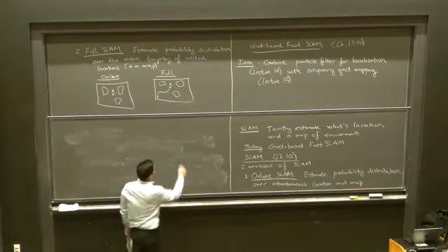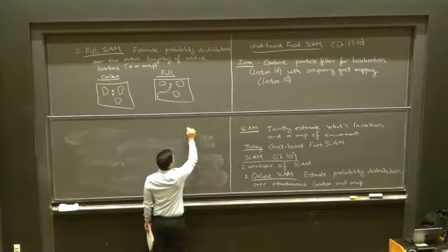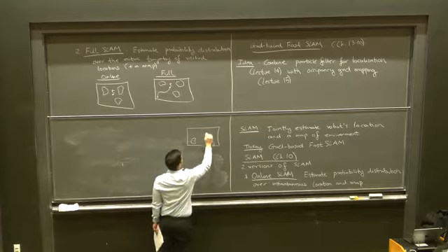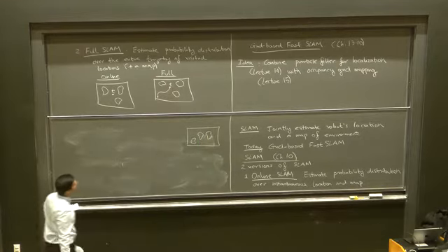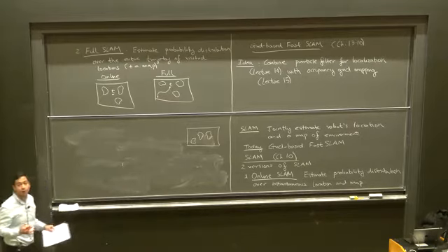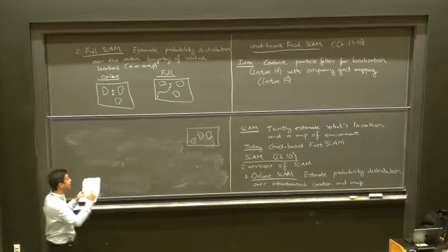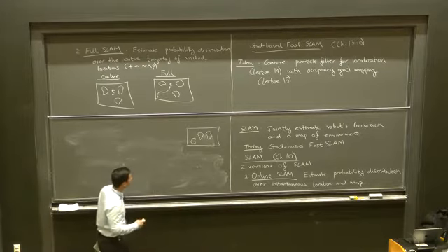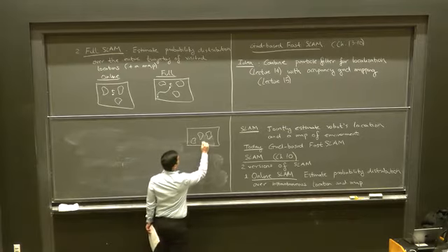So for localization, the picture was, well, I guess we were assuming that we have some map of the environment, so we know what the obstacles look like. And the particle filter maintains this approximate belief, this approximate distribution over the robot's possible locations in the form of a set of particles.